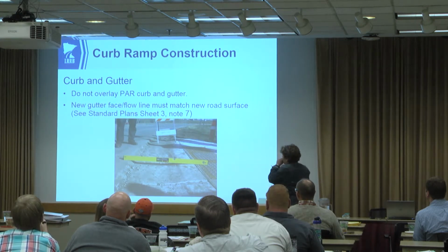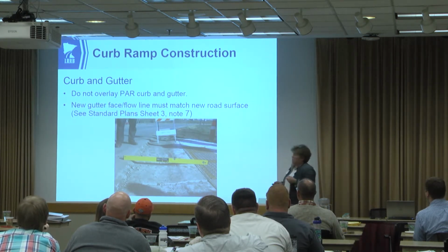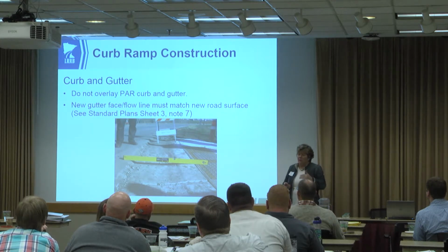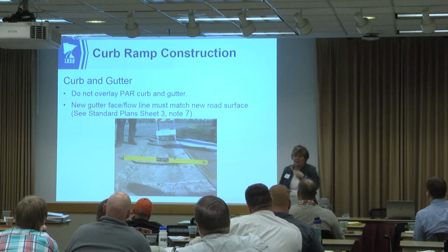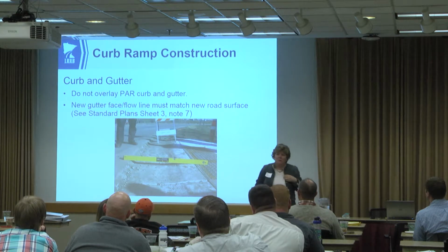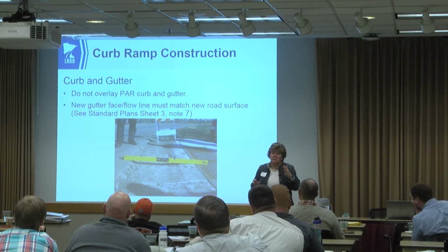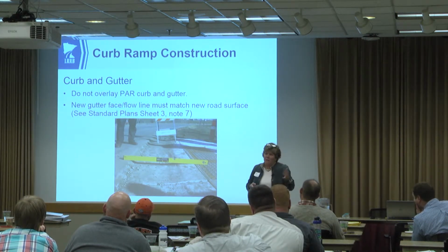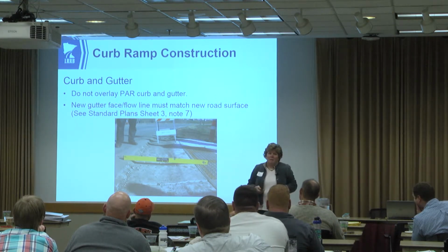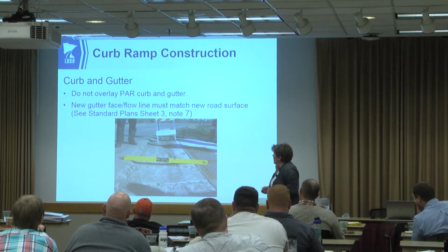Don't overlay the curb and gutter. And remember that the cross slope, the gutter grade, must be maximized at 5%. So we have all kinds of adjustments in the gutter and in the pedestrian access ramps. In an intersection, it might require quite a bit of design in the office, but it's well worth it when you get out into the field.